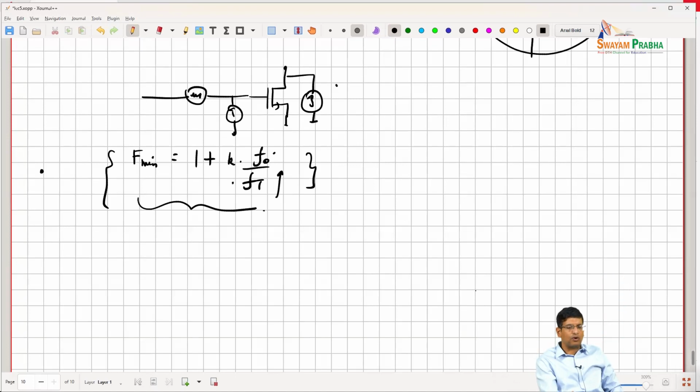But at its core, I shouldn't do things that degrade my fT, right? And we saw early on in the device that fT did depend upon RS and RD. There was a degradation that happened because of that. And particularly if I add additional CGS and CGD capacitances, I'm going to degrade my fT. So I should try my best to not do that, right?